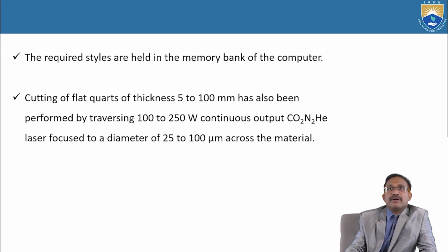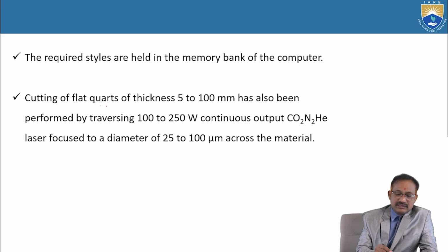Cutting of flat quartz of thickness 5 to 100 mm has also been performed by traversing a 100 to 250 watts continuous output CO2 and helium laser focused to a diameter of 25 to 100 micrometers across the material.